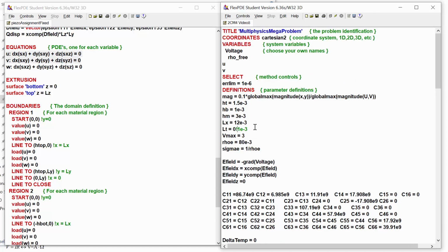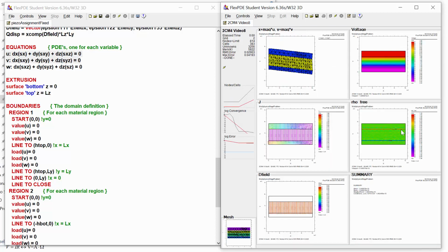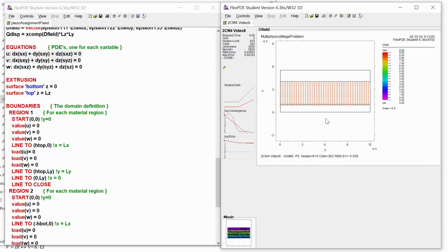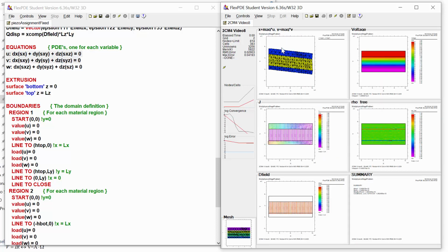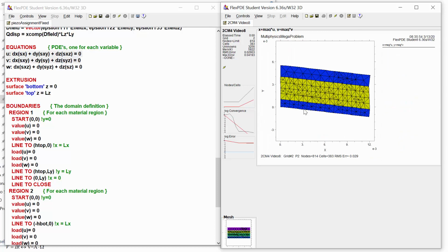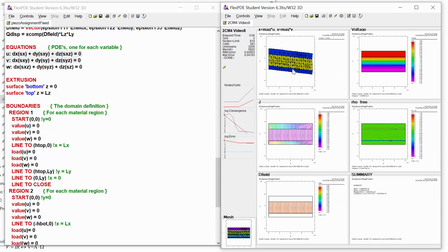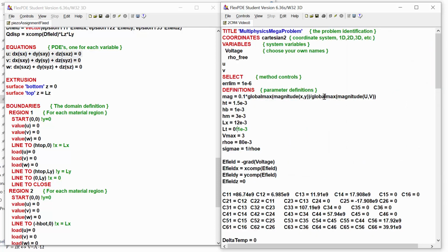So that would be if whatever electric field we have here, which in our setup is almost entirely an electric field in the negative Y direction, then we would be having a displacement, we'd be getting an XY shear strain, which is negative from a negative electric field in the y direction.